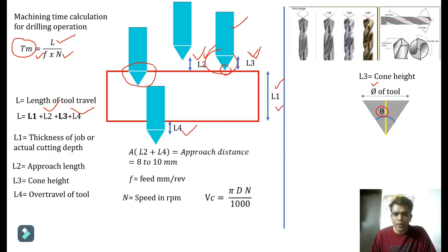As we are moving from one tool to another tool, maybe from carbide to steel, steel to carbide, and so on, the point angle is standard. It will vary from 118 to 125 to 132 based on the material of the tool. We can see this is the point angle, right? It may be 118, maybe 130, maybe 135.